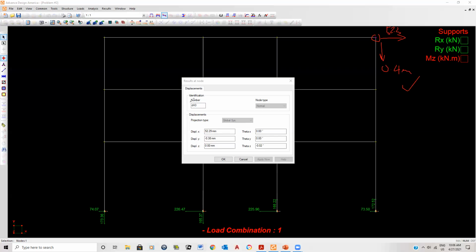And of course, you've got to be very careful and make sure your columns are oriented in the right direction, and so on. The reason I ask you for the displacement, at this point here or at this point here, whatever it is, is just for me to quickly check that all the members you put in have the correct member size. On top of that, it checks whether you've oriented them in the right direction, because if the members are in this direction versus this direction, you can tell right away that the displacements would be much higher, since these are much weaker to resist. That's why I asked you for those displacements, to make sure that you model everything correctly.